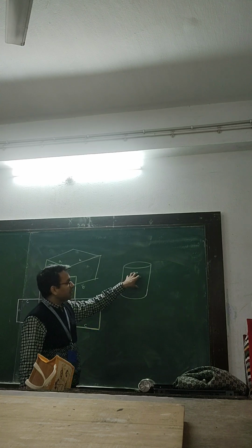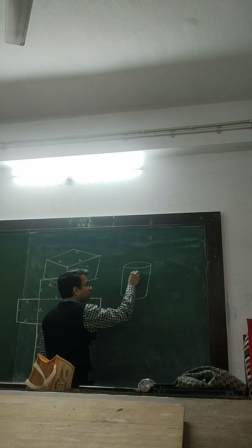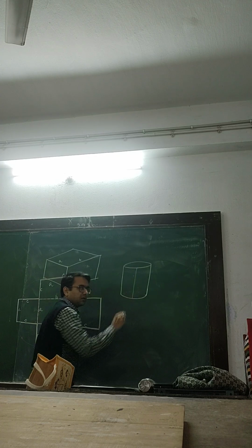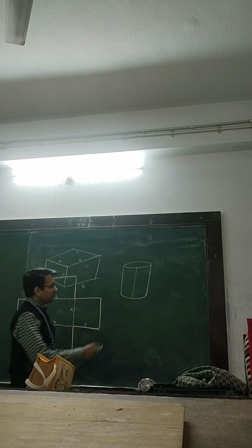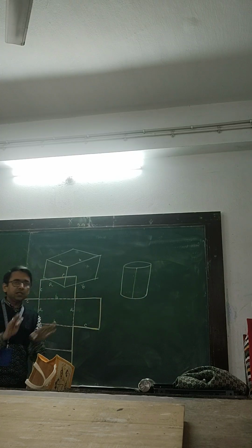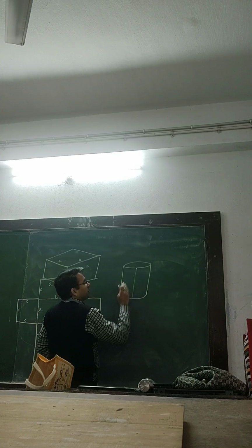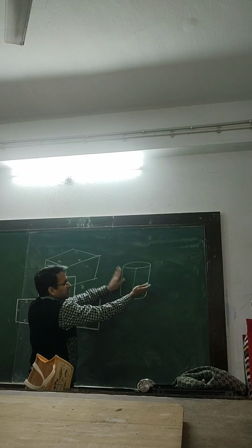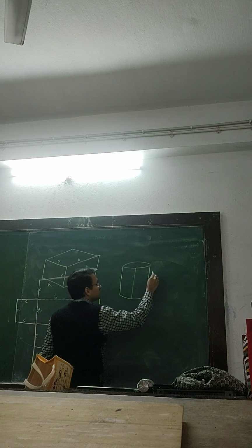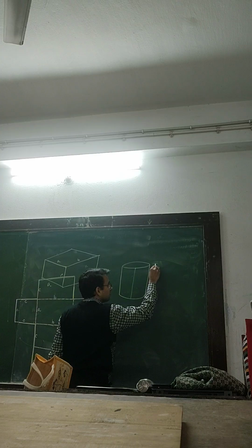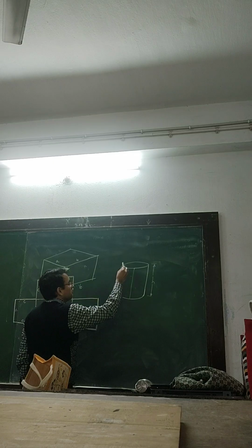Similarly for this, if I have a cylindrical surface like this, I know that I have to make a weld, right? Say for example, if it is a metal one, I will weld. Welding means initially it was cut, then I will weld. So what I will do basically, I will unfold. In the final form it is folded, but actually it is unfolded like this. So therefore I know this length. So this is say L or H. And this is R or D.